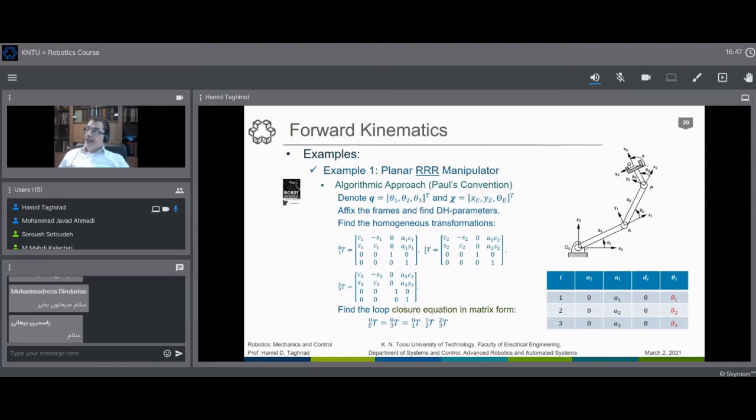And then the red vectors were the consecutive transformations that we can get by the joint angles and joint parameters. These are written by these 3 transformations here. We have found these by the Denavit-Hartenberg convention, and we simply multiply them all together.